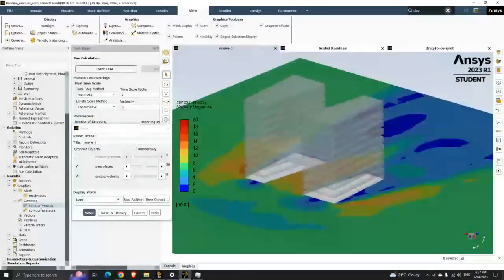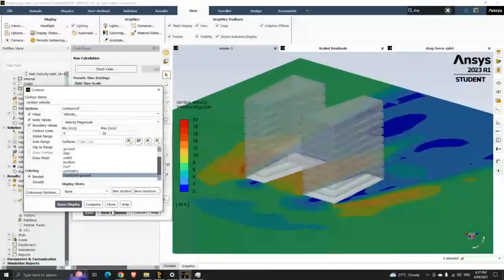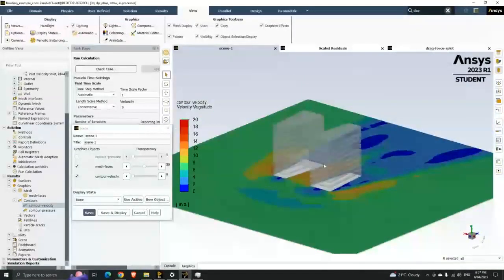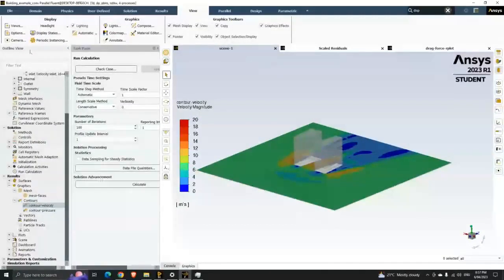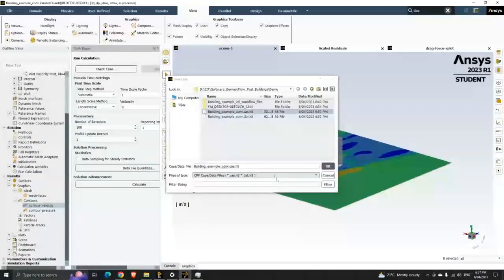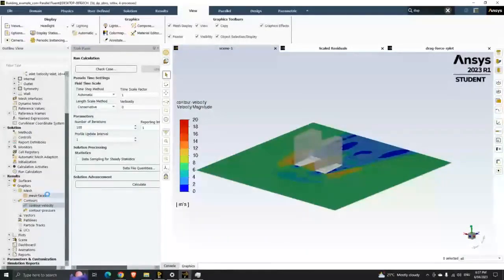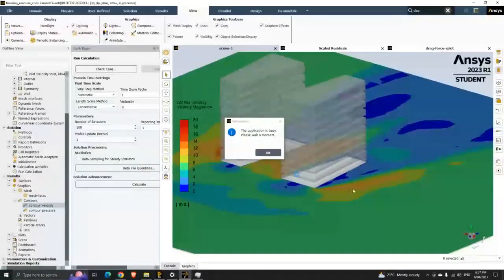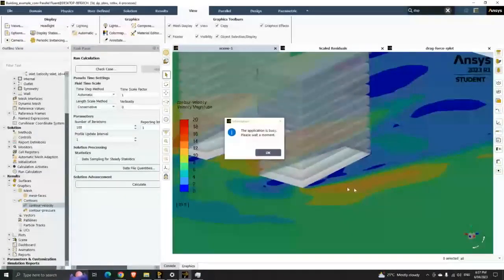You can also do the transform on other surfaces as well and look at the velocities. Okay, let's save this again, and I have another 3 minutes. What I will do is show you how to create path lines. I'll show you what's causing this flow acceleration.